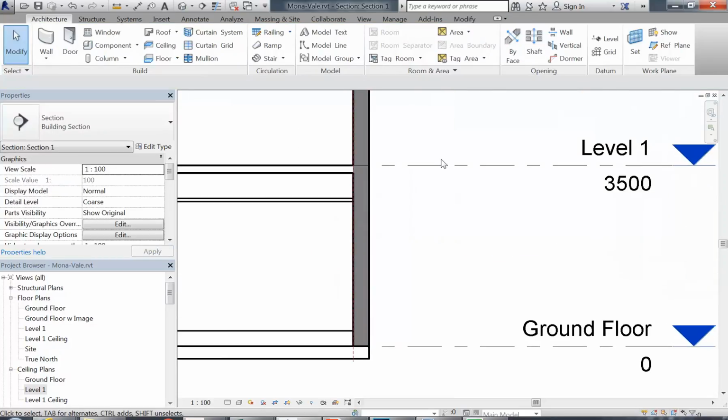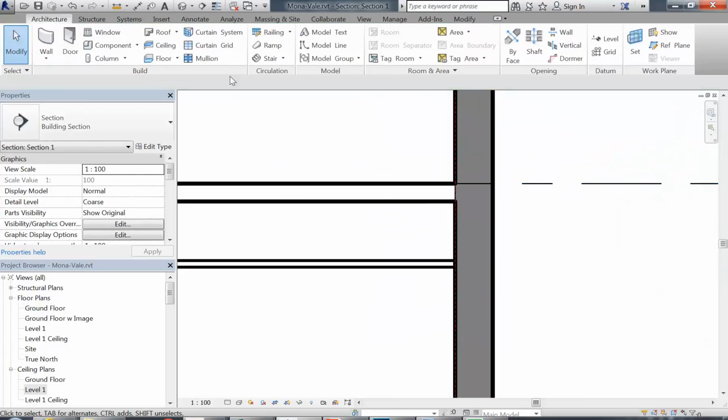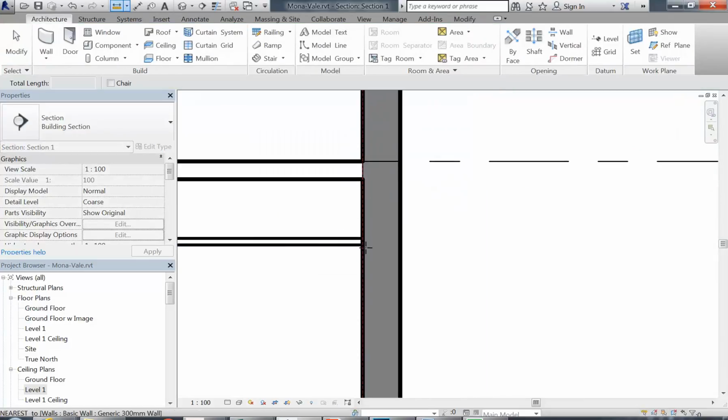And then we can maybe assume, because you don't have measurements, we have to assume, and I can say, well, based on the type of building it is and other things I've done before in similar buildings, it might be about 500 from the ceiling surface there to the floor above. Maybe it's less, maybe it's more, but probably you can assume here 500 is not too bad. So at the moment it's 700.